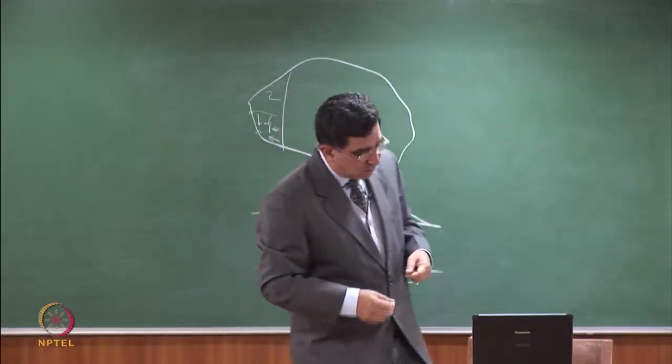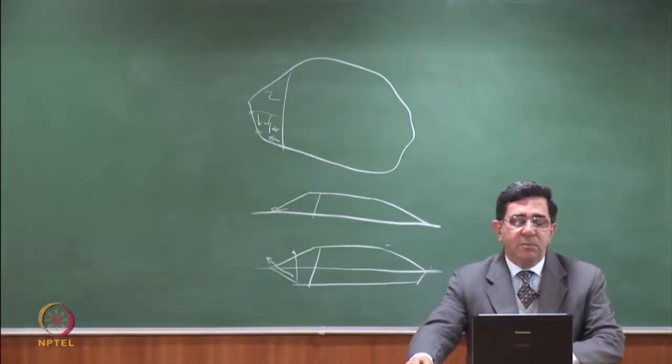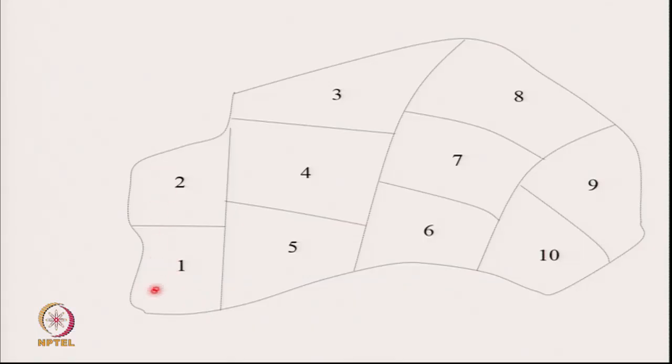So our thought process is that we can put the leachate wells, I'm only going to discuss 1 and 2, somewhere here and somewhere here, right? So let's look at what he says. So we have looked at 1, 2, 3 and 4. So what the designer has suggested is 1 here, 2 here, 3 here, 4 here. So all the leachate will come here. Please remember, the leachate of 2 will go here, the leachate of 3 will go there, and the leachate of 4 will go there. So this will be kind of a ridge, the high point. Okay?